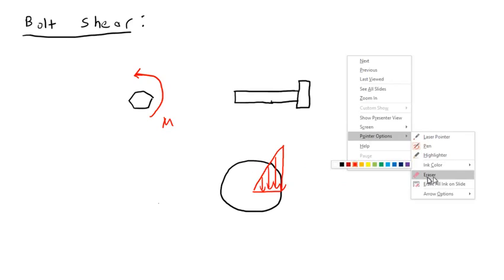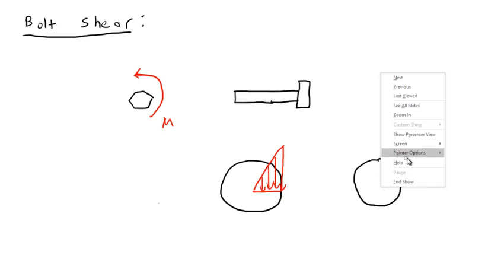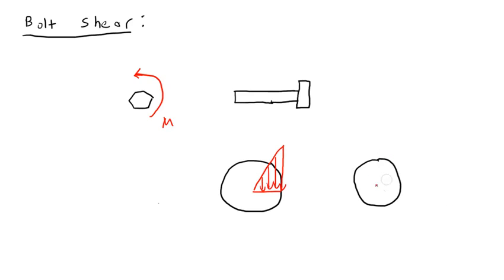But then if you add a plastic condition up to the limit of the bolt, up to say the elastic limit, you could have something like this, where you're just torquing the hell out of it all the way to the plastic limit. And shortly after this, you'll have passed the ultimate strength of the bolt, and that's where the thing just gives up entirely, and you just take the head right off the bolt.